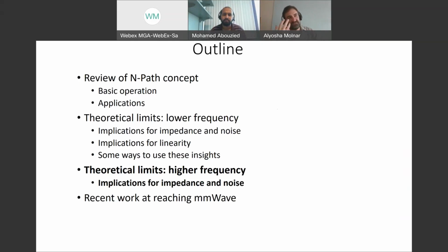What you can see, sometimes you'll see things that look kind of like that, but you can also explain that as just that same interaction with a non-real input impedance. If your input impedance is complex, then we get that shifting of the peak we saw before, and that manifests as something like a phase rotation on the baseband output. Those are related to each other.